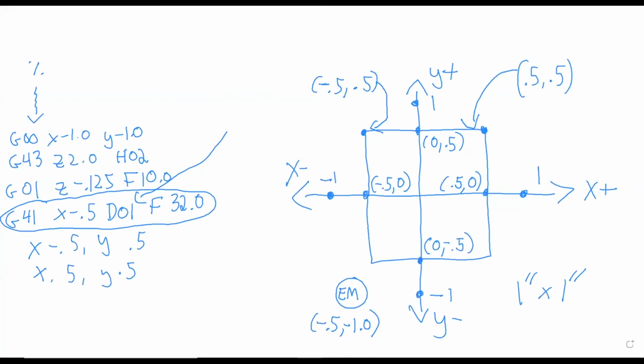I also mentioned the 2 cutter comp codes, G41 and G42, how they compensate the tool to either the left side or the right side of the cutting action. Notice that I have used G41. So this is going to compensate on the left. What this means is the direction of our cutting path, the tool will be compensated the radius of that diameter to whatever side that we call out. In this instance, it's cutter comp left.